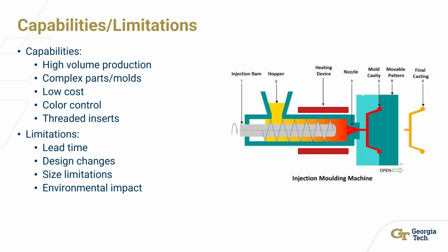Some of your limitations are lead time because you do have to create different molds. Design changes are very tough because then you're dealing with having to make a different mold for the product. Size limitations, obviously you can't have too big a mold or else that does create issues. And then environmental impact, you are creating a lot of different molds that sometimes cannot be reused, and thus you're almost stuck with them. But overall, great technique, one that I've become very familiar with after researching the first two products.